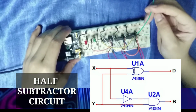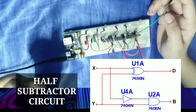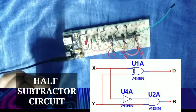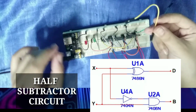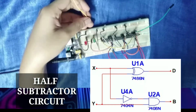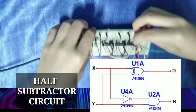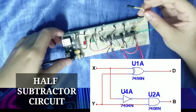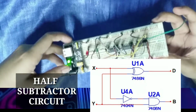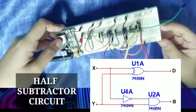And the second input will be the input Y, which will be our yellow wire here, and it is connected to the second pin of the 7486 integrated circuit. So this will be our connection for our half subtractor circuit.